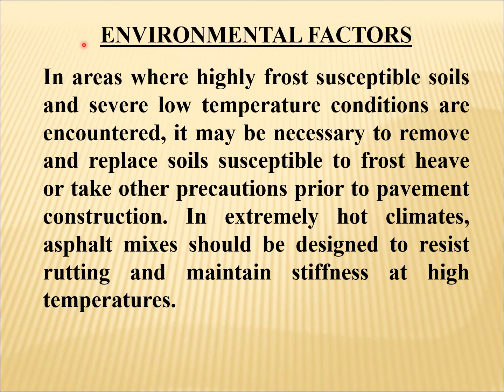Environmental factors. In areas where highly frost susceptible soils and severe low temperature conditions are encountered, it may be necessary to remove and replace soils susceptible to frost heave or take other precautions prior to pavement construction. In extremely hot climates, asphalt mixes should be designed to resist rutting and maintain stiffness at high temperature.